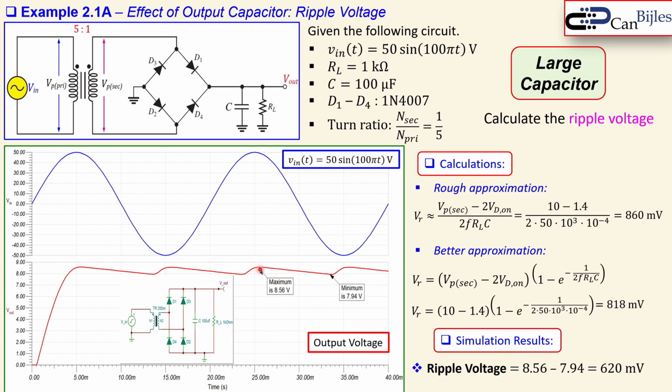It is a little bit smaller. You can see that. This is the peak, but it actually starts to increase again before this part, which is then the half of the period. So I need to make this 1 over F actually smaller, and then you will have a more accurate result for your ripple.